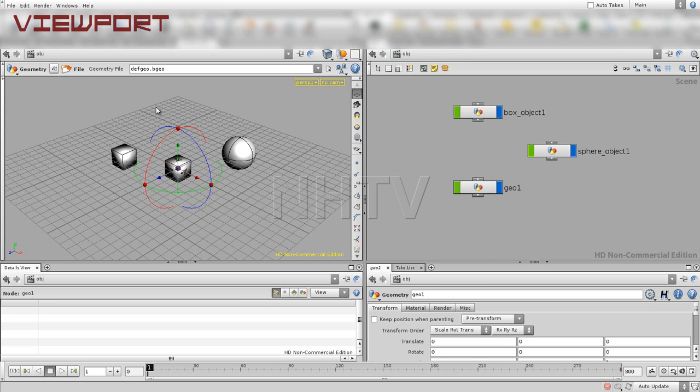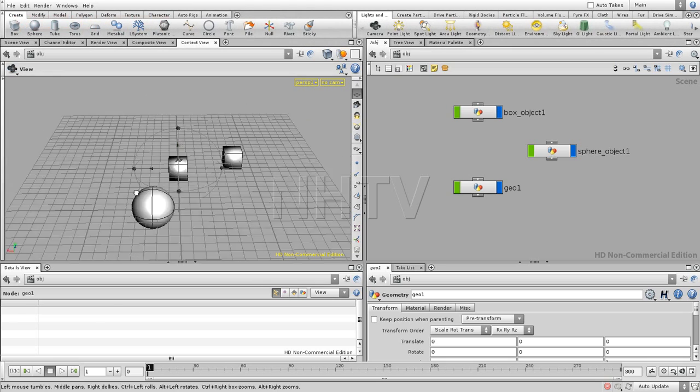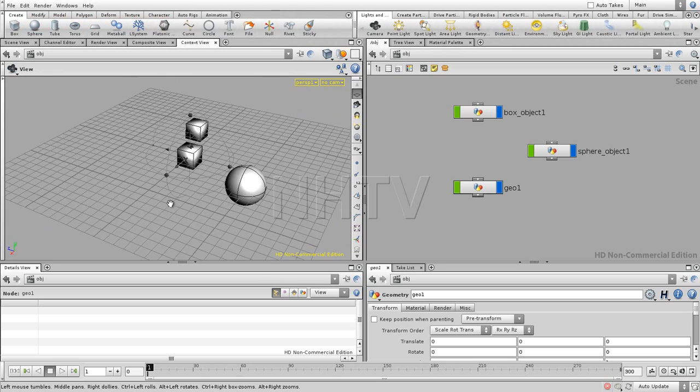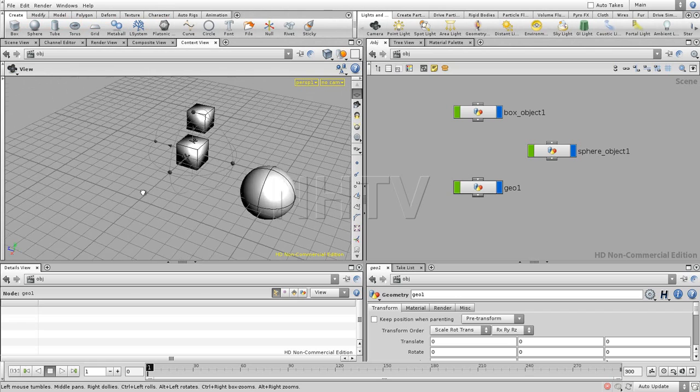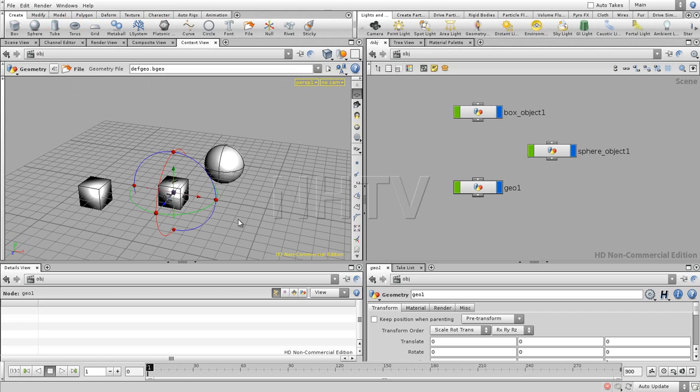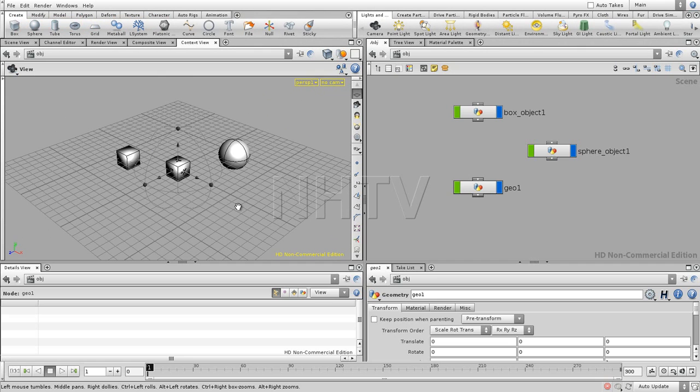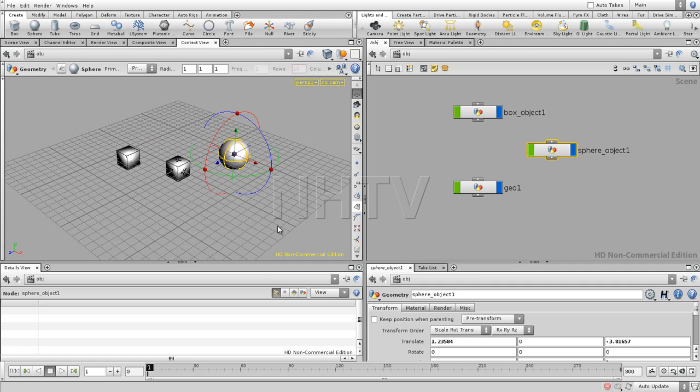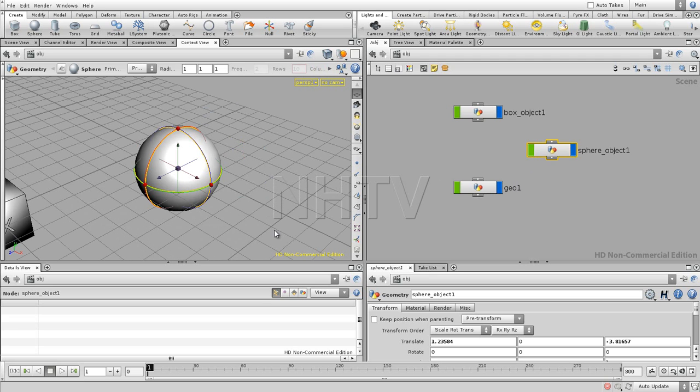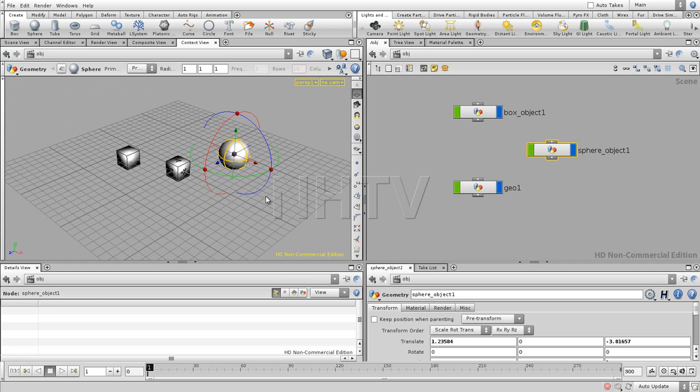Alright, the viewport. Like in Maya, like I said before, using the spacebar, left mouse button is rotation, middle mouse button is move, and right mouse button is zooming in and zooming out. There are some shortcuts. You can press the spacebar H and it's going to go to home, which is this view, or you can select, for example, an object and press spacebar G, and then you zoom in on a particular object. Right, so this gives you a little bit the controls.